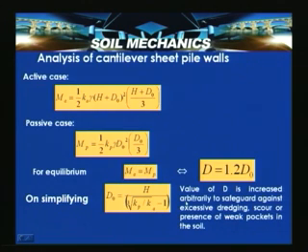So, the value of D is increased arbitrarily to safeguard against excessive dredging, scour or presence of weak pockets in the soil. The value of D is increased by about 20% to safeguard against dredging or scour or presence of weak pockets within the soil.